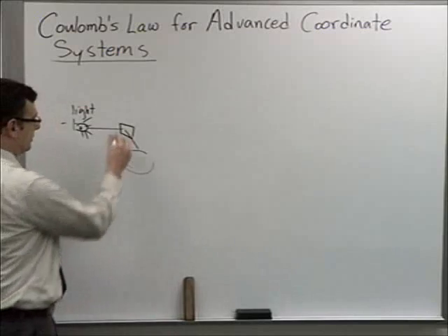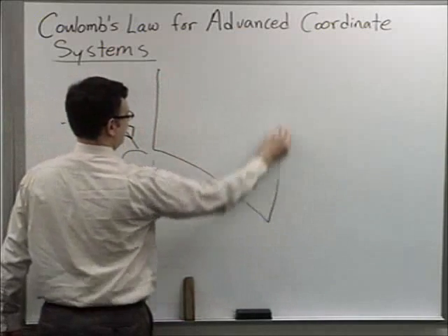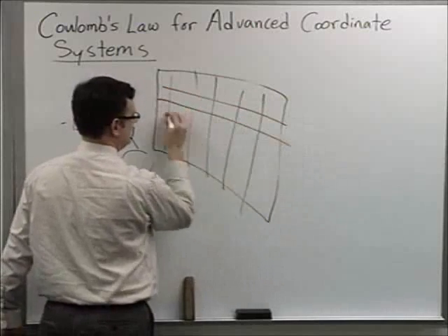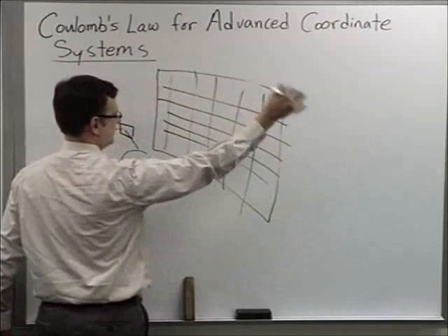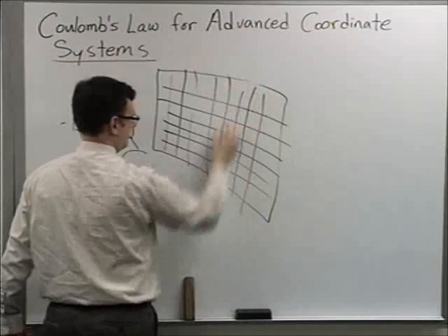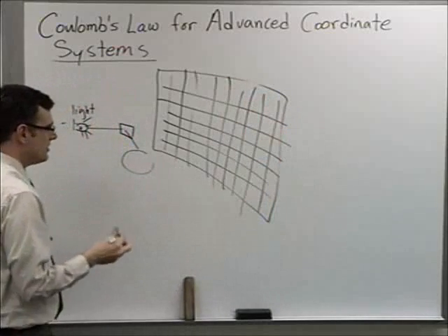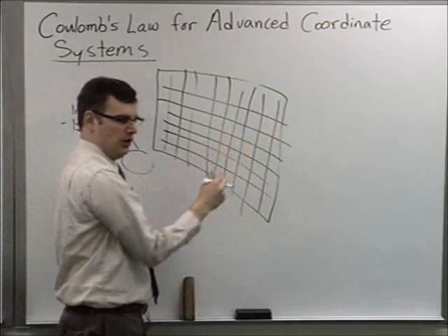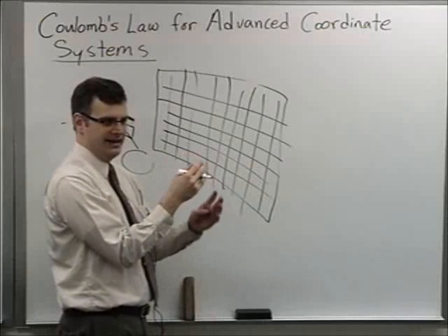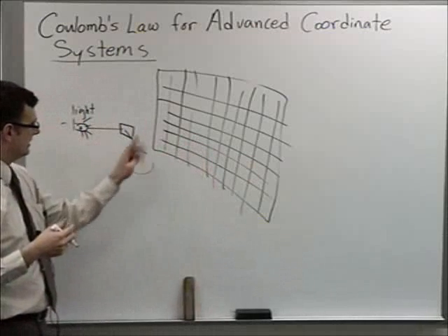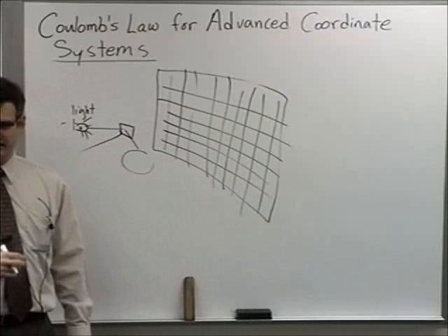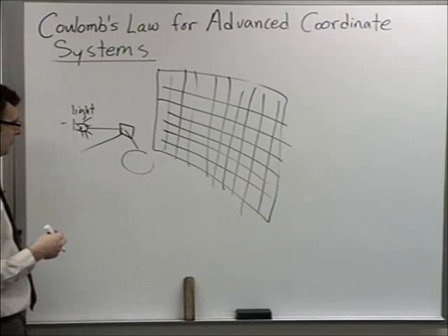But if you blow this thing up, what they actually have is a bunch of mirrors, tiny little mirrors, 1,000 something by 800 something or whatever resolution you're using. And these mirrors are on pivots. So if you apply a voltage, you can deflect them. When you reset them, they come back and will reflect the light through the lens. If they deflect, then they're just deflecting light off in a direction that you can't see it, towards, say, an absorptive area inside the projector.